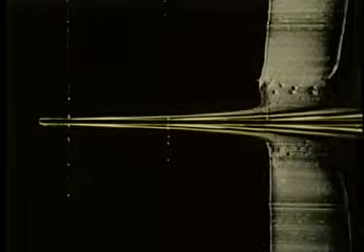Viscosity acts through the mechanism of molecular diffusion to spread out the vorticity as it is convected downstream. The local boundary layer thickness is a measure of the distance vorticity has diffused away from the plate. We can relate the factors controlling this growth process in the following simplified manner.